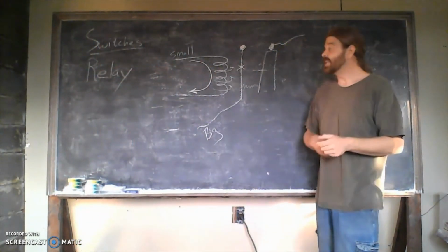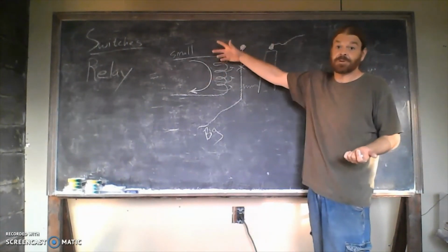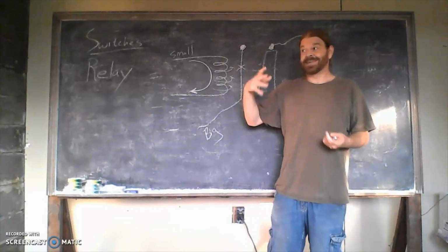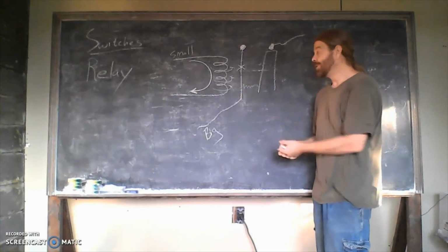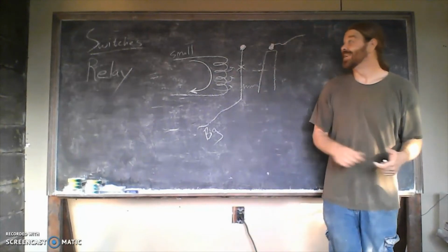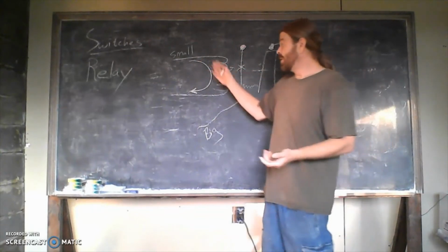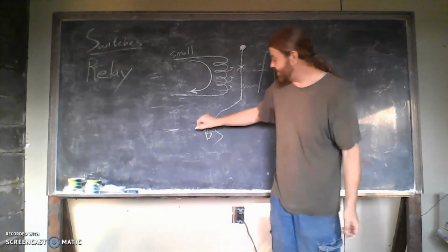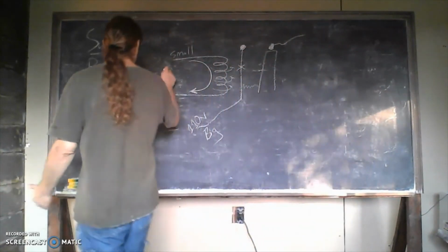And this is the one I wanted to include because that's going to be very important for IoT stuff, right? Raspberry Pi is running 3.3 volts. ESP8266, that's a Wi-Fi chip, which has been expanded into its own microcontroller. So now instead of hooking the Wi-Fi chip up to a microcontroller, the Wi-Fi chip is a microcontroller now, which is pretty sweet for making IoT stuff. But the small voltage, 3.3 volts, or up to 5 volts, is not enough to turn on a coffee maker. Most of the stuff in the house is going to be 110 volts, right? Whereas all our microcontrollers are going to be less than 5 volts.